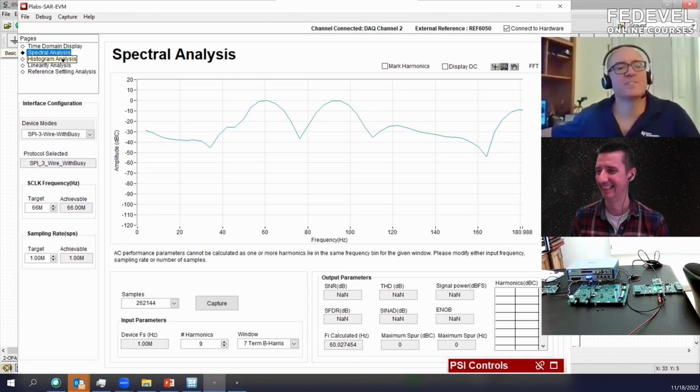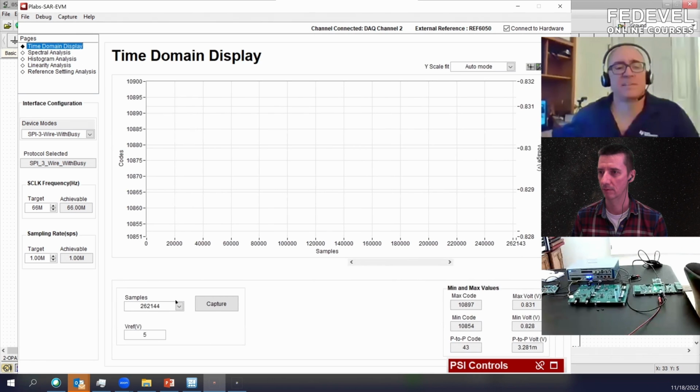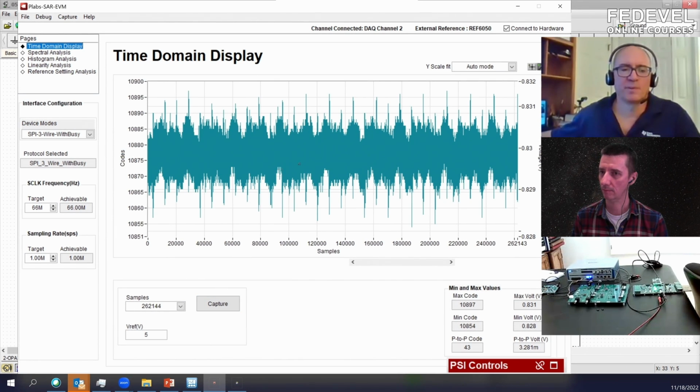And then let's look at the histogram. The histogram still looks Gaussian, but in fact, it's not completely Gaussian. What is a little different is the tails of this histogram are much further out. So if you look at the peak-to-peak value here, it's much higher than it would be for the normal 60 hertz noise. And just depending on the conditions of your room, whether the lights are on or off, where your wires are sitting, you can make this worse or better. And that's the dangerous thing about the 60 hertz. Sometimes when people do low noise measurements, they'll turn off all the lights nearby and try to minimize the power, or run things off of batteries if they have to, or use a shielded environment as well.